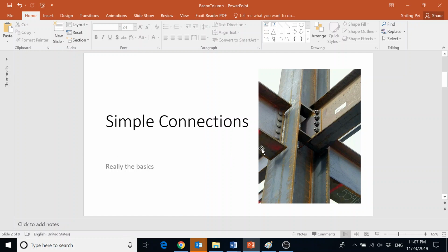There will be other types of not-simple connection designs, which will involve maybe when those bolts are not loaded equally, when they're loaded by a force with a moment lever arm, so it's a combined force. And also later, if you want to get into seismic designs and connections, how to consider their ductility and everything, that's not so simple connections.